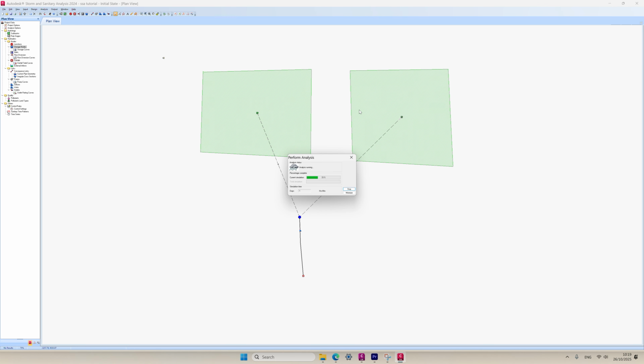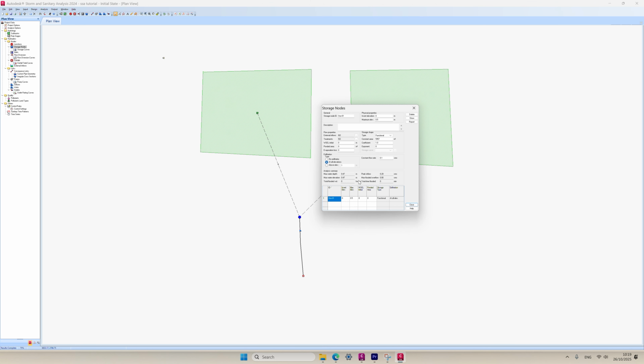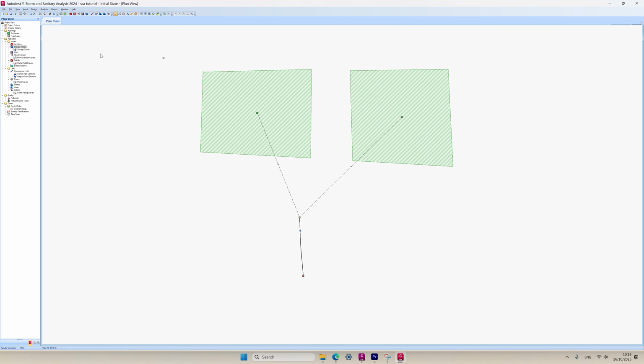So we'll just close and run the simulation again. And now we could see it didn't flood. So the total flood time becomes 0, and the max water depth goes to 0.47, just right below our elevation of 0.5.